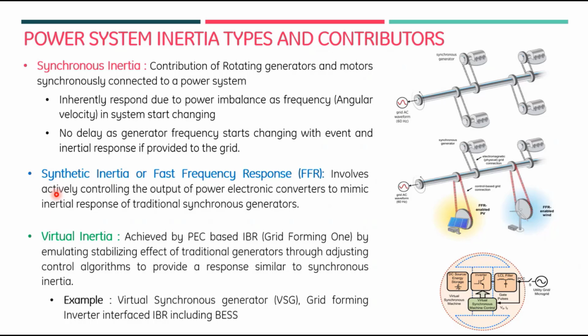Then we have a concept that is now coming with the grid forming inverters. That is the concept of virtual inertia. Basically, you mimic your IBR so that they respond like a synchronous generator.